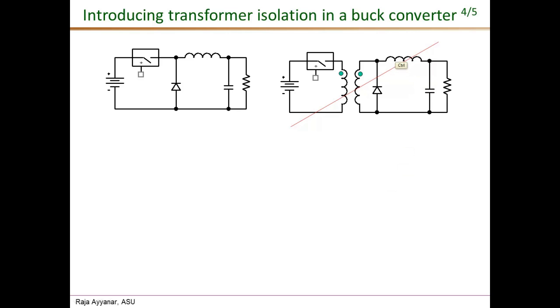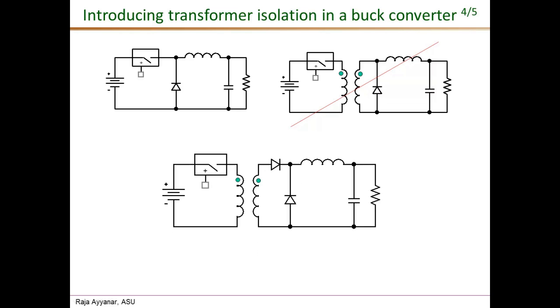Okay, so then we see that it is this diode directly across the secondary which is causing a problem. It violates the volt-second balance. And this diode is really needed to have freewheeling for this inductor current. The inductor current needs a path when the switch is off. So we cannot eliminate this. So let's prevent this short circuiting of the winding by the diode during the off interval by putting a diode at this point. So that is shown in this new schematic.